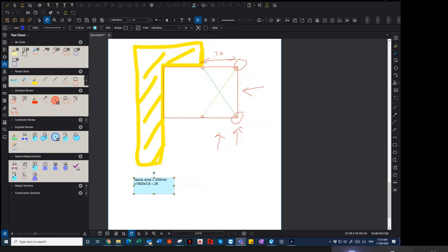Still fails, isn't it? Yeah. A 90 by 90 F7 is very flimsy. Even if you are holding a 3 meter post lying horizontal and you try and push in the middle, you could feel the flex, and it's very flimsy.